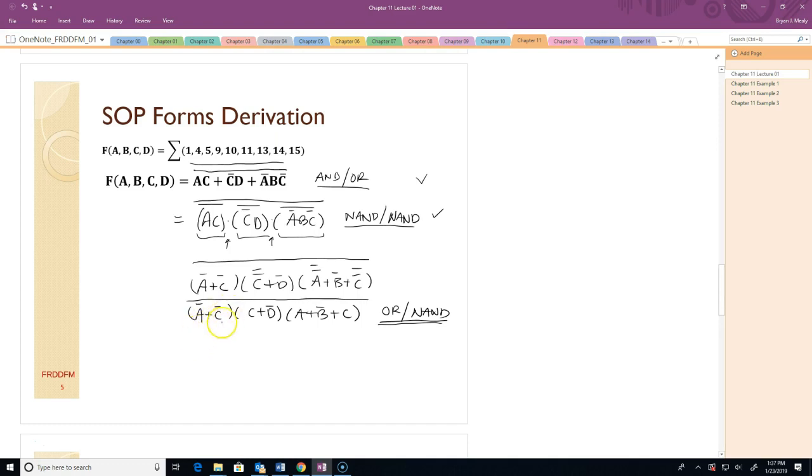Okay, so the next step here is I'm going to take this overbar down, and this is going to be A. Check that, make sure it actually does look good. It actually does look good. And this is another classic form, which happens to be, I see these two terms being ORed together with the overbar, which is a NOR, and then these things are being ORed together right here with no overbar. That's an OR. So these inner terms are NOR, they're being ORed together, so that's my classic NOR-OR form. Once again, I can't say I've ever seen that anywhere, but I know how to do it.